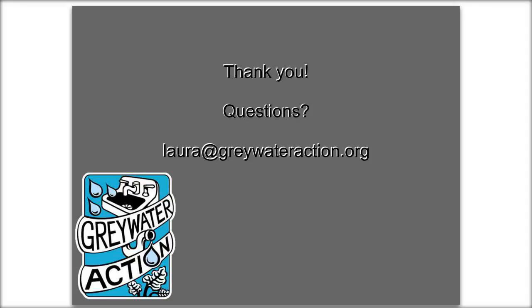So there's a question about water savings. That is a great question. So how do you track water savings with the graywater system? There are different ways to do it. If you have an existing irrigation system and you're going to be replacing some of your plants, so today they're being watered with fresh water on the irrigation system, and tomorrow when you finish your graywater system, they will now be watered with graywater. The easiest way is to replace an entire zone and then just shut off that zone, and then you'll know exactly how much water you are saving, because if it's a 3-zone system and you turn off one zone, you're now saving a third of that water.